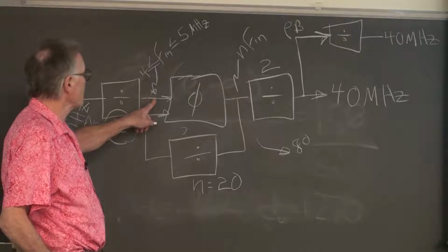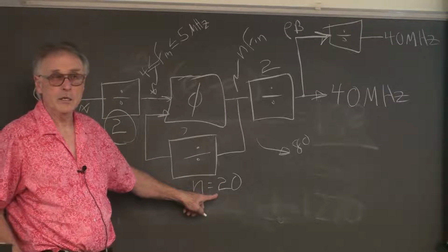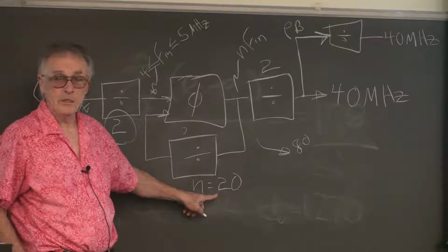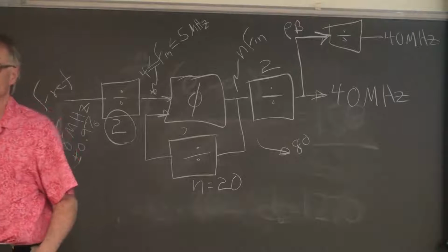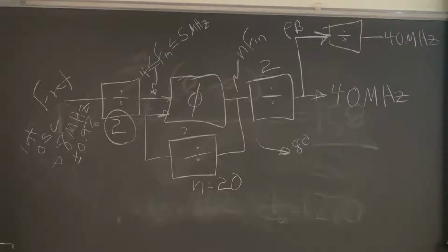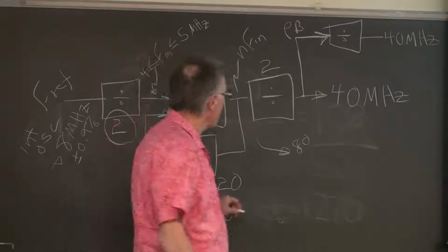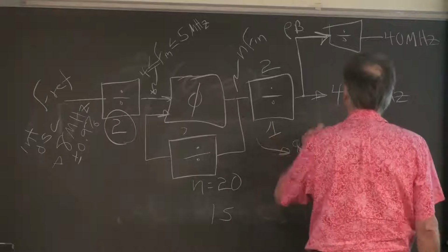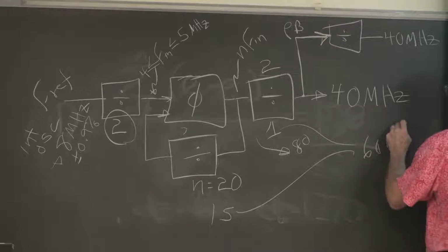4, that's 4 megahertz there, times 30 is 120. If you can set this to 30, and I'm sure you cannot. So what are the other possibilities? 15 and 1. So you could set this to 15 and this to 1, and now the output would be 60 megahertz.